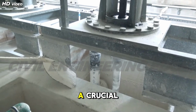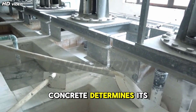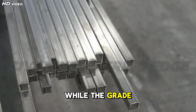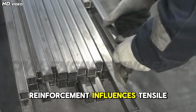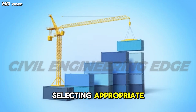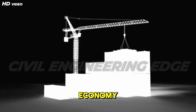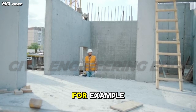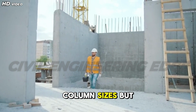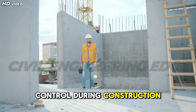Material properties play a crucial role in column design. The grade of concrete determines its compressive strength, stiffness, and durability, while the grade of steel reinforcement influences tensile capacity and ductility. Selecting appropriate material grades is a balance between structural efficiency, economy, and construction feasibility. For example, higher concrete grades allow for reduced column sizes, but may require stricter quality control during construction.